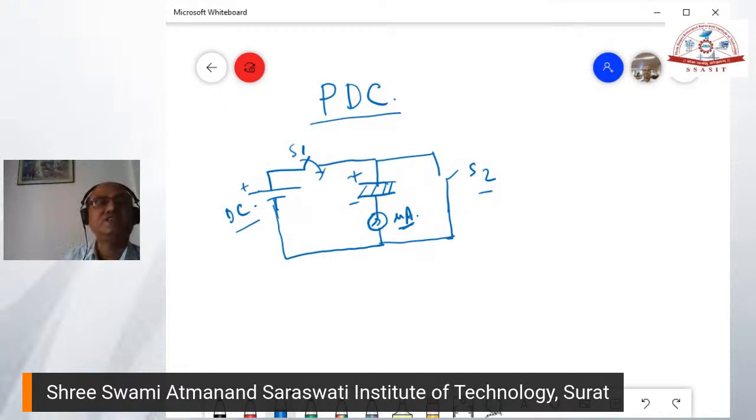On the transformer, to check the component-wise insulation: core, magnetic path, and conductor. Out of that, insulation is the weakest part. So insulation condition monitoring is done rigorously. In polarization and depolarization, this current is the first one.